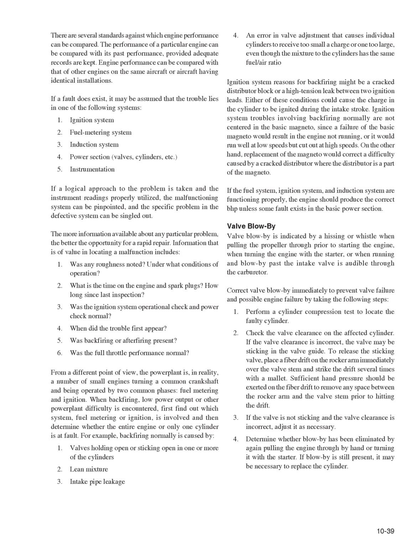Valve blow-by is indicated by a hissing or whistle when pulling the propeller through prior to starting the engine, when turning the engine with the starter, or when running, and blow-by past the intake valve is audible through the carburetor. Correct valve blow-by immediately to prevent valve failure and possible engine failure by taking the following steps: 1. Perform a cylinder compression test to locate the faulty cylinder. 2. Check the valve clearance on the affected cylinder.